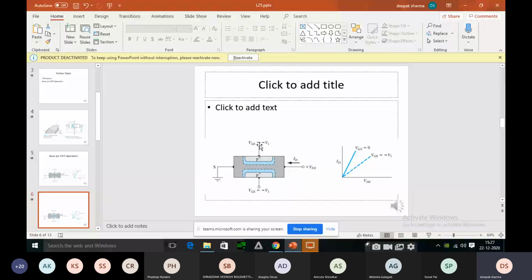But the other thing, when we increase VDS, yes, the current will increase. Current will increase here as we increase the VDS. Correct. So that thing is very clear, but the level you are seeing here, at this particular point, the level is here for the second case, but the current level is high in the first case.